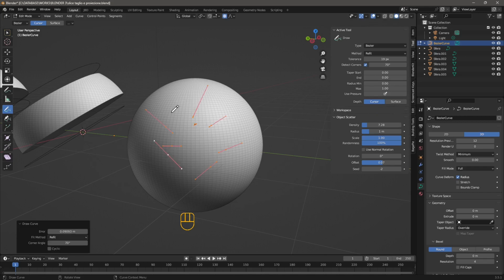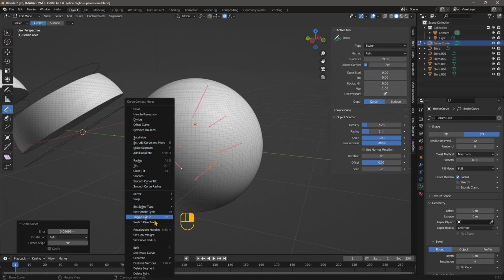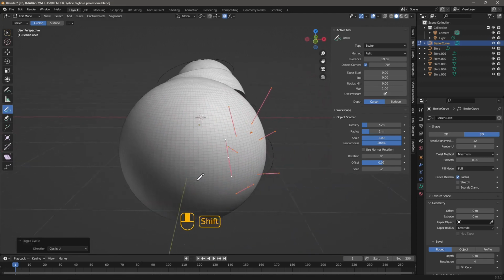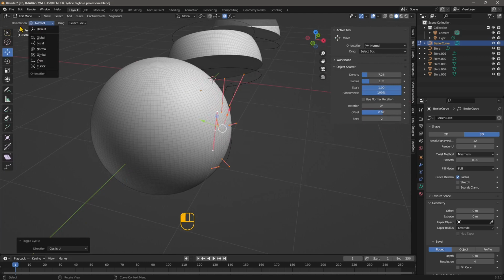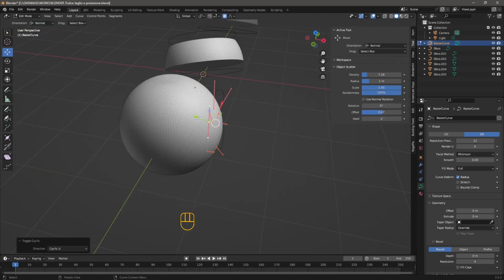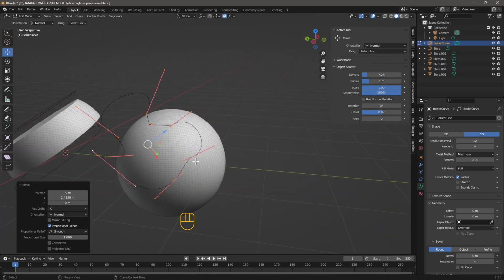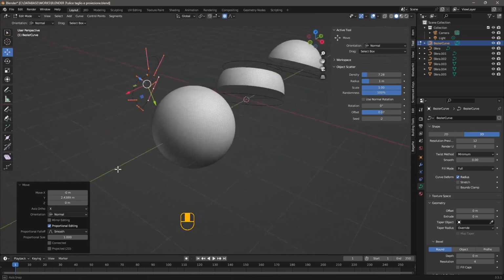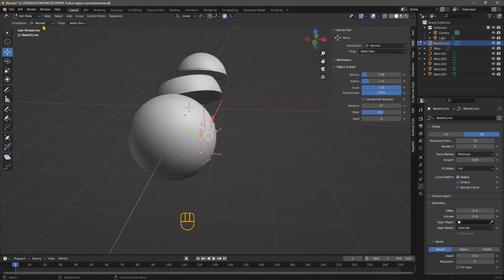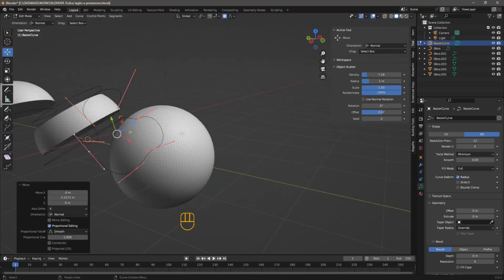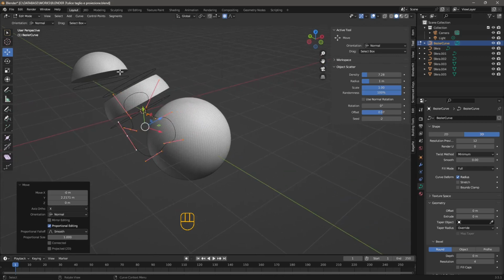Okay, let's say I want to create this shape. Now remember also that you want to close it, so right click and do toggle cyclic. So that is going to create a closed shape, which is now right here, and I want to move it. So I'm using the normal orientation to move it on the front. So I'm going to move this here. Okay, now probably we need to adjust it. Let me just go back and try, not global, but well, yeah, maybe the best one here is normal. But essentially, we want to bring this to the front, and we want to extrude it.